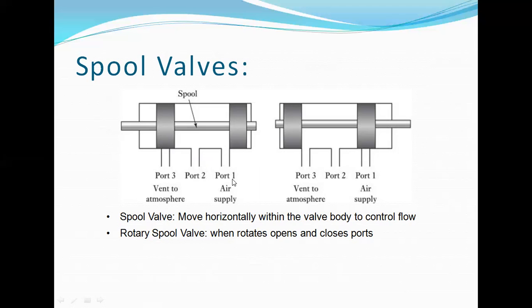In pneumatic operation mode, compressed air is supplied. When the spool valve is completely extended towards the right side, port 1 continuously drives. In the second condition of the same spool type valve, when port 1 is open, it supplies only to port 2, and simultaneously port 3 will be closed. If it is in open condition, it is directly released to the atmosphere.